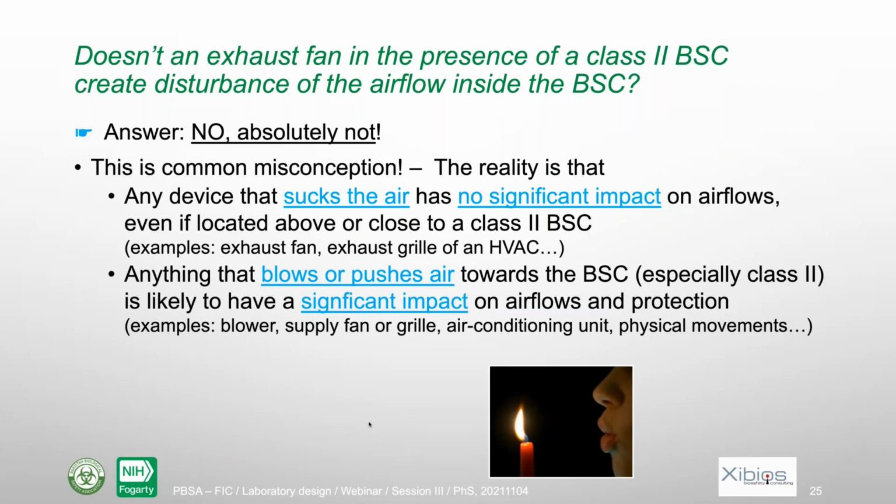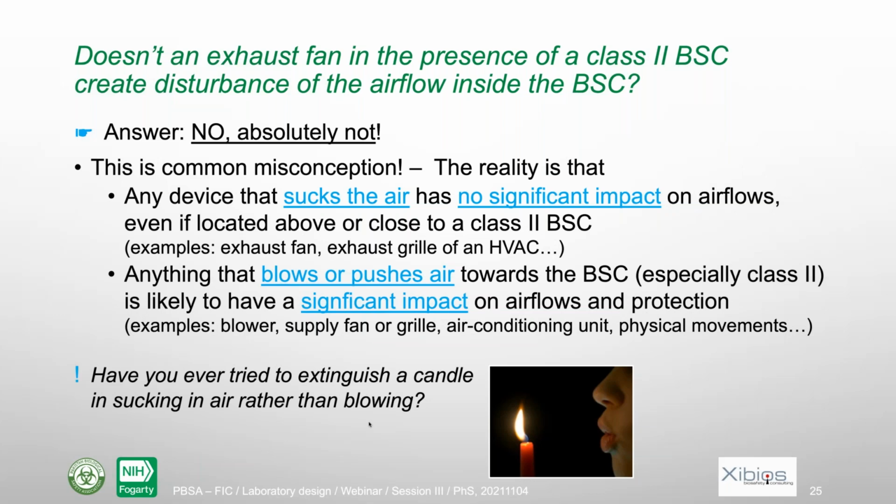You can only extinguish a candle if you blow, if you push the air towards the candle. If you suck the air, it's impossible to extinguish a candle. So try to remember that image of extinguishing a candle. Only the air that is pushed will disturb the biosafety cabinet, not the air that is sucked.